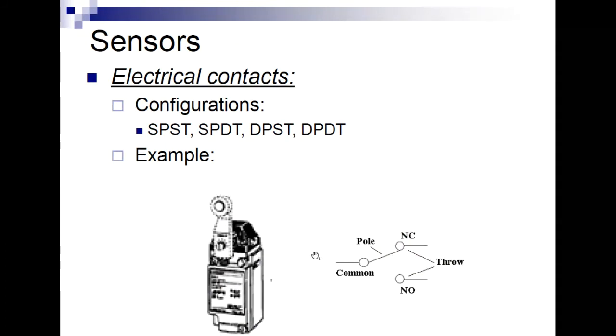the voltage, whether it's 24 volts or 120 volts or whatever, that's coming in here. You don't really see it. Those are the wires coming into the box. All right, and so right here, you've got this arm on the limit switch that's going to move. And this arm, you see right there, that screw, this arm is attached to the pole. So when this arm moves down, then this pole is going to come over here.